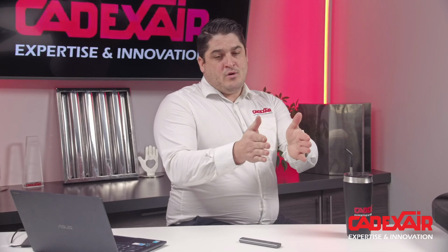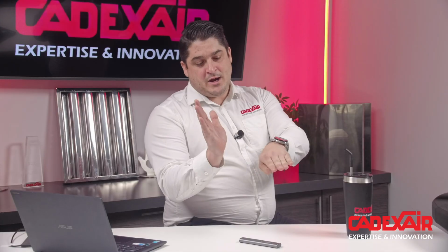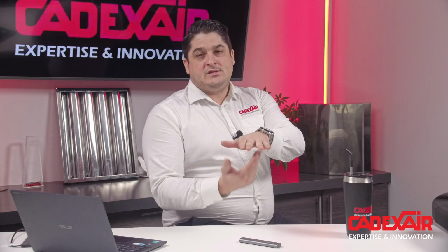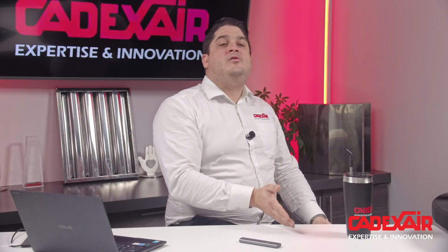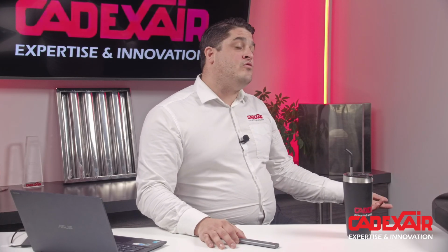Yes and no. Like I told you a little bit earlier, if we bring the filter a little bit to the front, it creates a gap here. Often the cooking appliance will be right under, so what could happen is the smoke and the grease can create condensation or a little bit of grease accumulation. We can put a 45-degree angle in between. So yes, we can move a bit, but we always need to double check. Or if we have to move too much, we can do a V-bank section that can be installed in the middle of the hood.